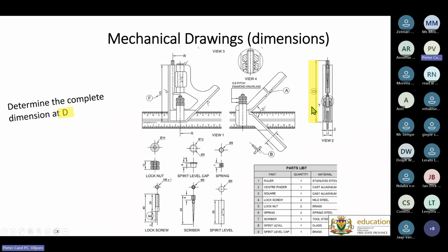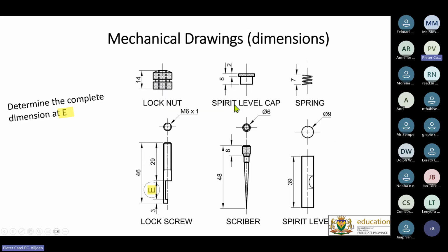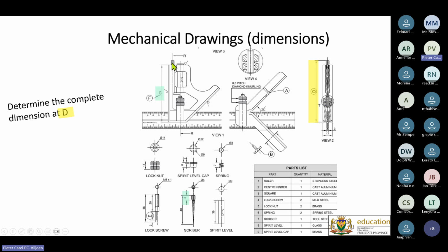All right, the height of it, sometimes you have to build it. Over here it says 103, but you must remember that that little knob is not this one per se, it's this one over here, and it says 8. So you have to add the 8 millimeters to the 103 millimeters, which is basically this plus that part over there, and that gives you the total height of that part. So that becomes a middle order or even a high order question, because it's not all in the same line. It's not given there, but it's given as an auxiliary view.